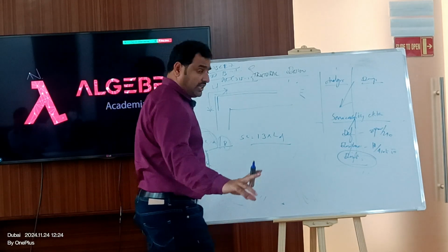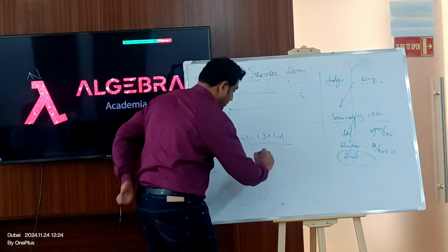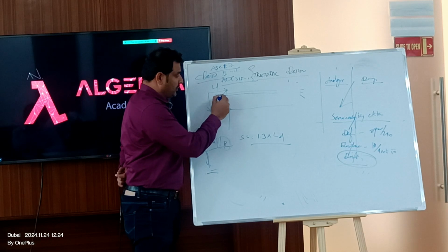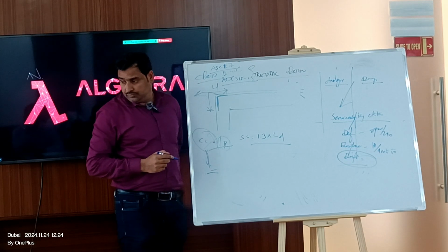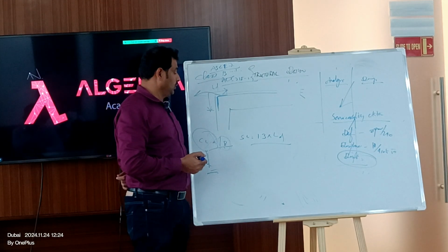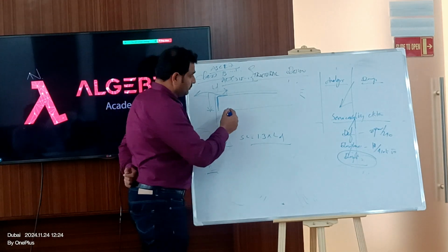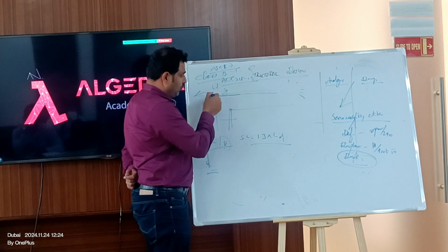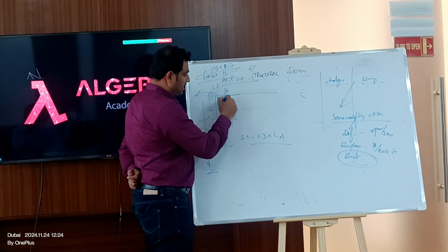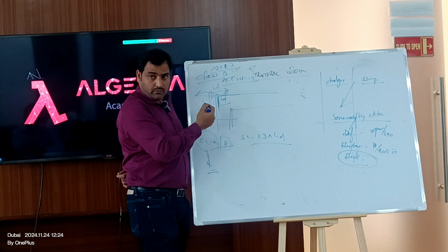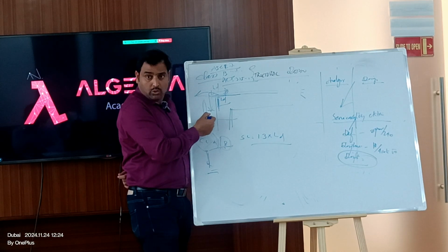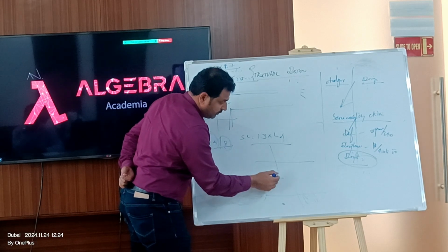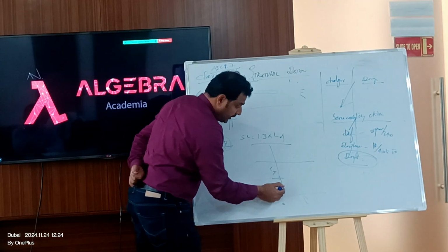There are two kinds of equations there. When you want to use it as a hook, then you have to use a separate equation. Okay, I can show you. Or else, if the shear wall length is higher, then I can compensate with straight rebar as Ld. Straight rebars, so you don't need to take it all the way. The similar approach you are going to follow in the raft as well. This is the Ld.